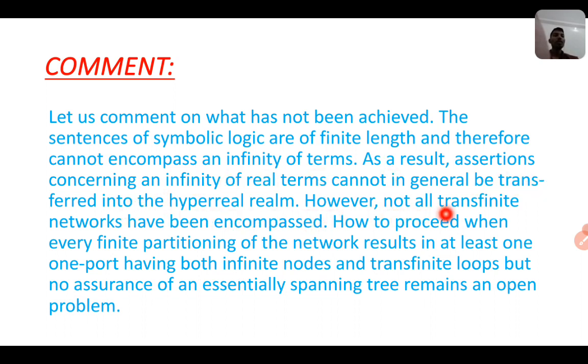However, not all transfinite networks have been encompassed. How to proceed when every finite partitioning of the network results in at least one one-port having both infinite nodes and transfinite loops, but no assurance of an essentially spanning tree, remains an open problem.